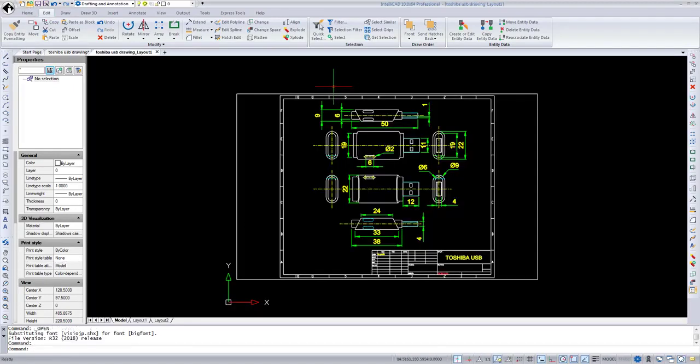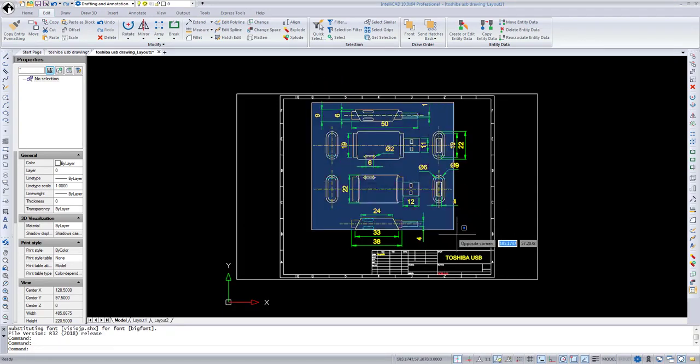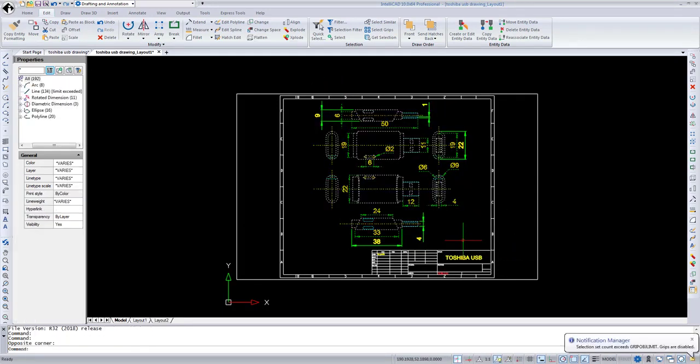Exported objects are 2D entities allocated on the Model tab. These entities can be exploded, scaled, copied, and trimmed. The command is not available from the Model tab while in Block Editor, during reference editing, or while using a maximized viewport.